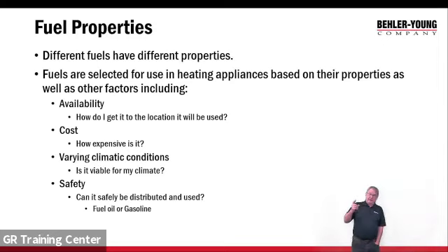Propane below 50 below zero will not vaporize anymore. If you're living in a place that's 50 below zero, you probably should move. But if you're living in that place, propane might not vaporize, so it might not work in those locations. So the climate we're using it in is also a consideration.